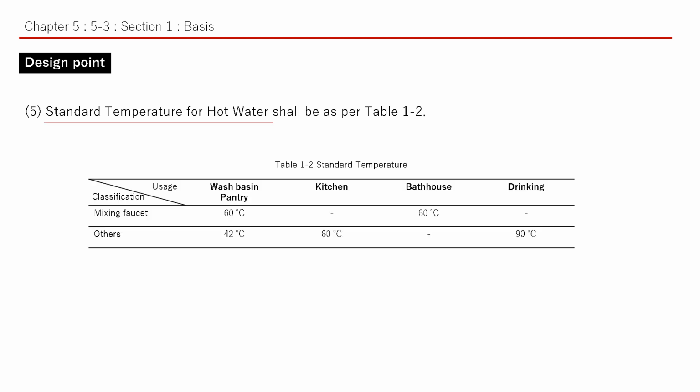Item 5. Standard temperature for hot water shall be as per table 1-2. As you are aware from table 1-2, we consider 60 degrees Celsius for keeping the hot water to suppress the outbreak of Legionella bacteria.